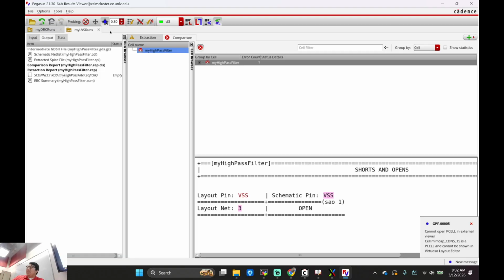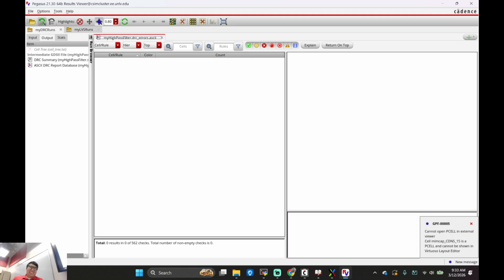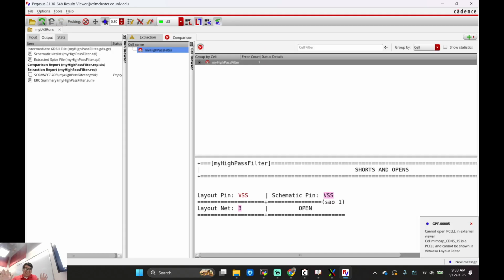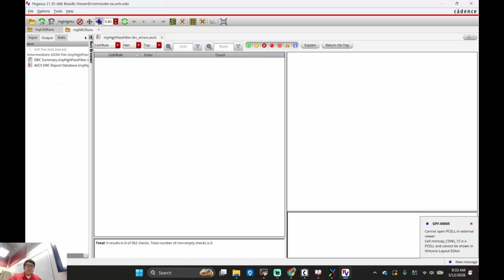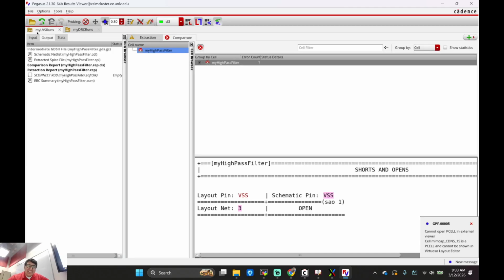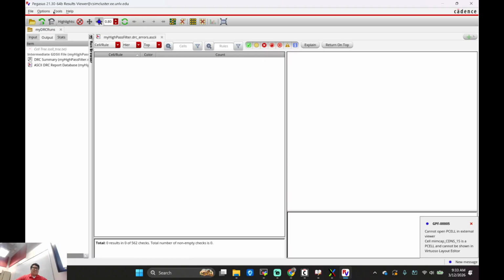You see how we have the results viewer? I'm going to click on this right here. My DRC runs, right? I'm going to press this button. See? You don't have to do that iteration again. You just run it and it lets it do its thing. It popped up. Okay, it DRC'd. Great. But now I need the LVS. See? You just click on the LVS tab, then hit that play button. Your life, like, boom, it becomes a lot easier. It feels good, but you at least want to have it LVS.